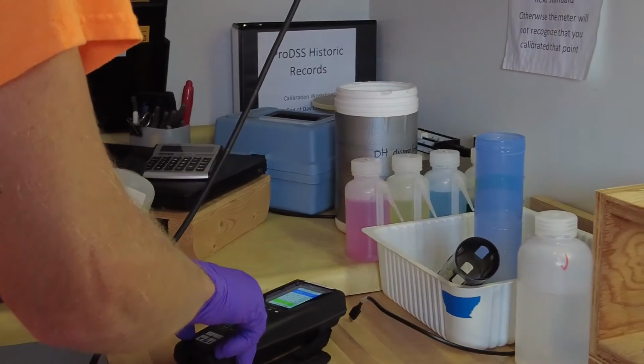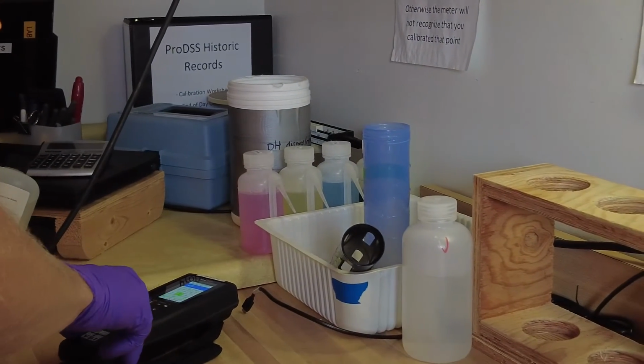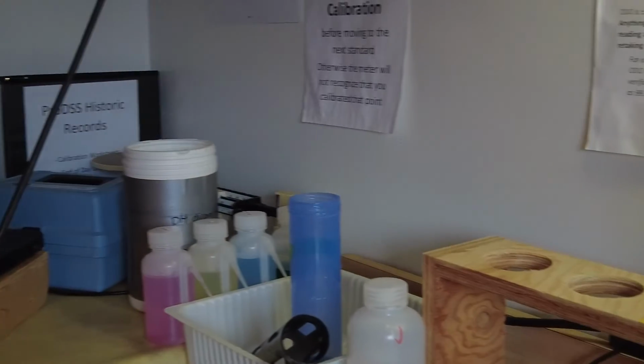And it's just like any computer program, garbage in, garbage out. If the information you receive is garbage, you're going to walk on it, and it's not going to hold you up. It's not going to work. So if you have field instrumentation, guard it carefully, calibrate it, keep it clean, because particularly pH and dissolved oxygen are key parameters, and you can get an idea of how a system works by intermediate measurements within the system. It's essential to keep that just pristine and ready to go and calibrated.